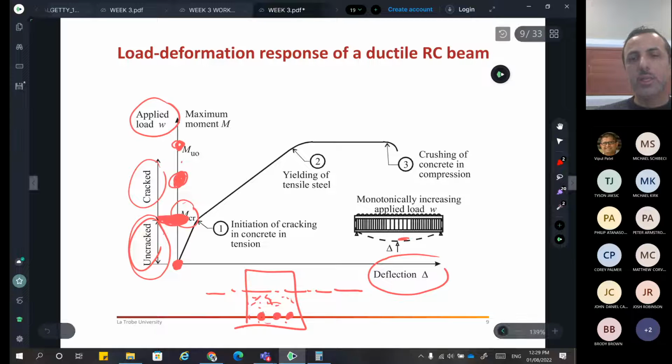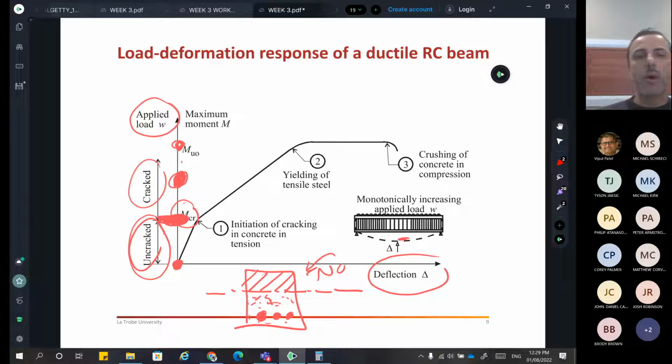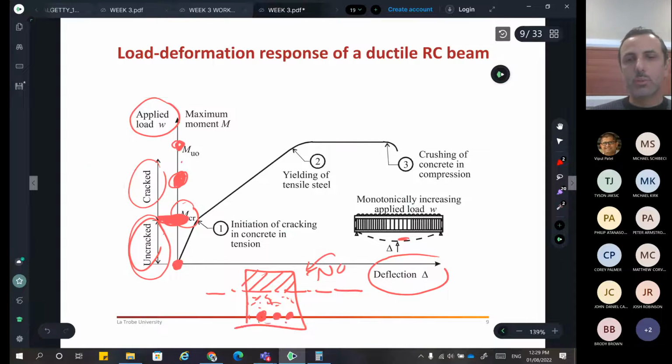When the cracks happen, then the steel gets into business and starts doing its intended job. Above the neutral axis, the concrete is still active. No cracks here. So when you hear us talking about uncracked and cracked, we're not talking about the full section being cracked, or those excessive cracks that we're going to prevent with the steel anyway. We're talking about those micro cracks, which are required, and we need to reach them in order to get the system engaged, and things will work correctly.